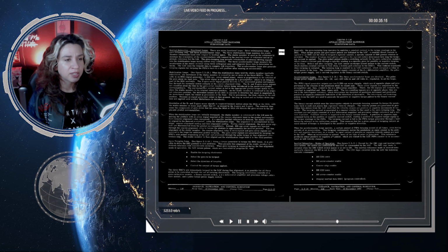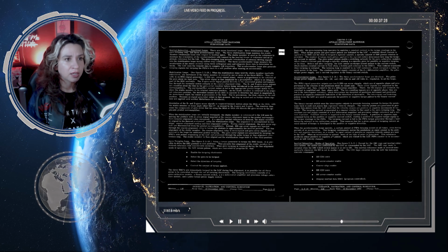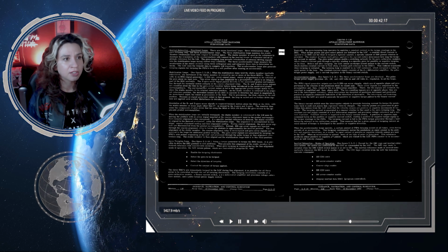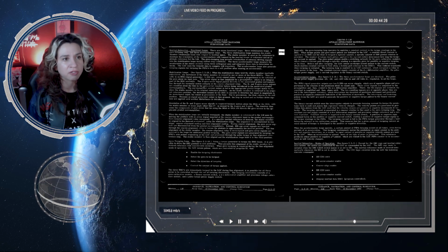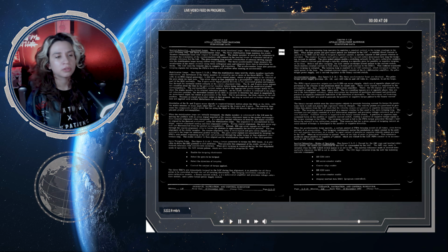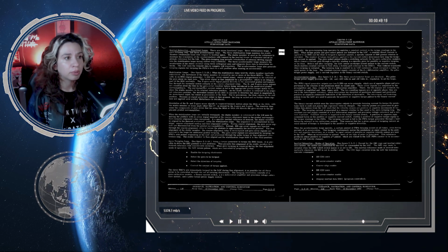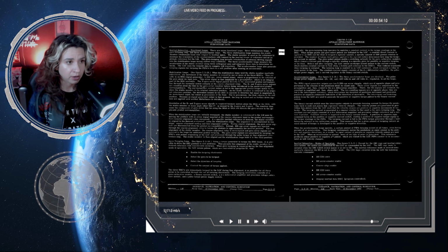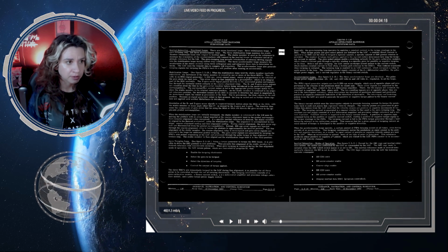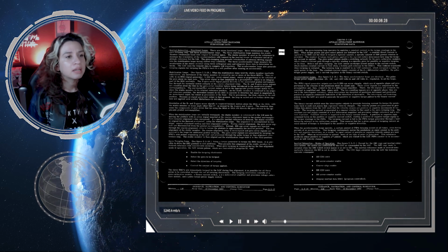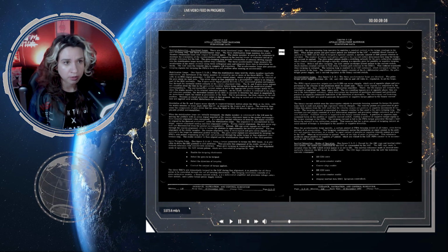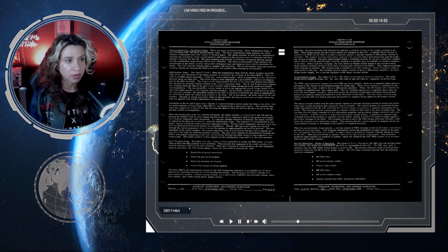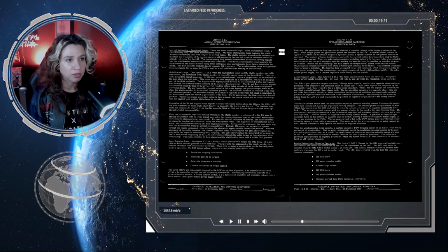The torquing loop is enabled by the LGC command, which energizes a relay, applying power to the loop. The constant current supply consists of the DC differential amplifiers, the pulse torque power supply, and the current regulator in the binary current switch. The 3 accelerometer loops are identical. The pulse torque power supply provides a positive 20 and a negative 20 and a positive 120 volts DC.